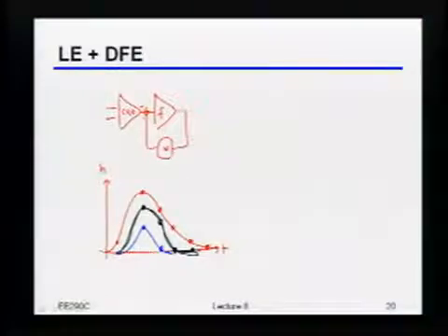By the way, another way of saying that this allows you to give up less on the DC gain is to say that effectively I've backed off on the bandwidth of my linear equalizer, right? Because notice, the width of this pulse coming out of the linear equalizer is roughly twice as wide as it used to be before, right? Approximately. I'm not exactly 2, but ballpark.